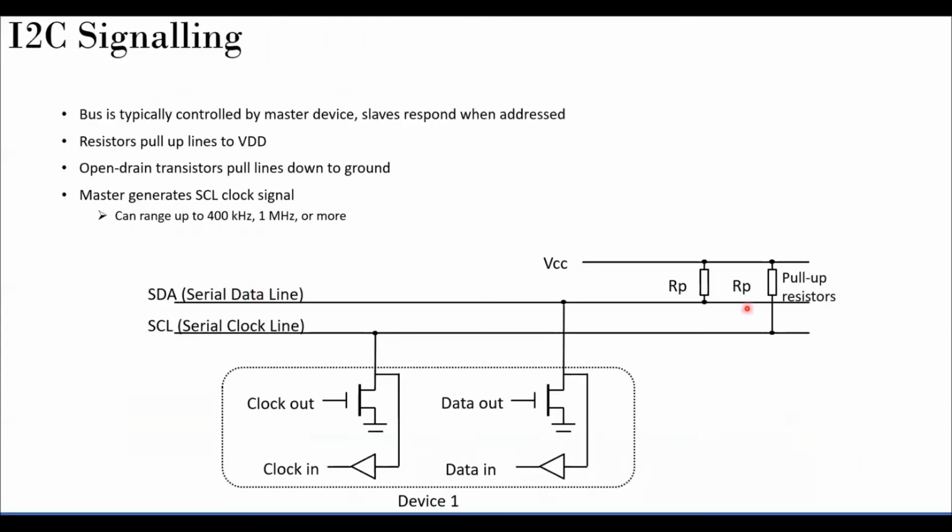So this is typically how it looks for an electrical engineer. The previous one is more for a computer science and electrical electronics mixer, but for an electronics electrical engineer, it looks something like this. And I think this is common for UART also. When I said, if you remember, the UART data line is always high, right? How is that possible? There are some resistors which are pulling it up to VCC all the time. Unless it is driven to ground, it will always be at a high state, okay? So that's the meaning of it.